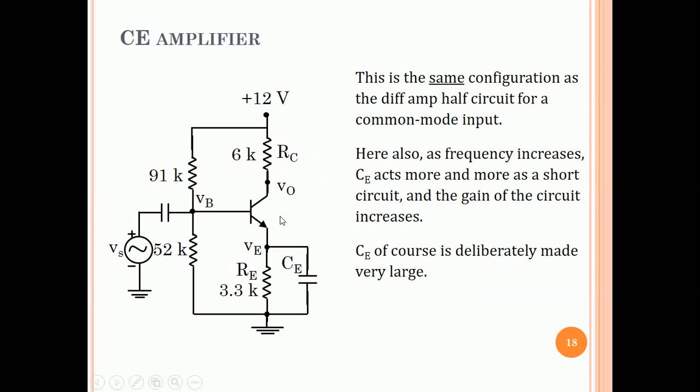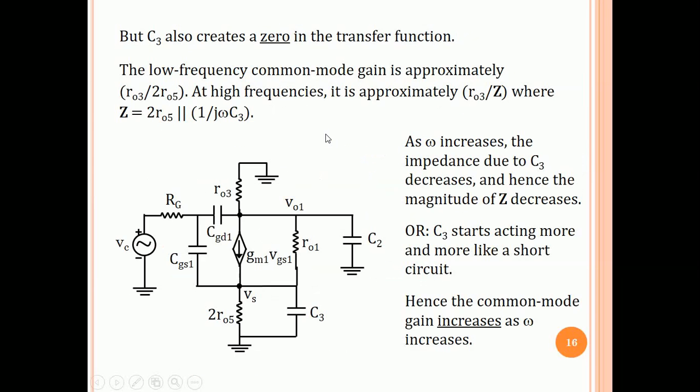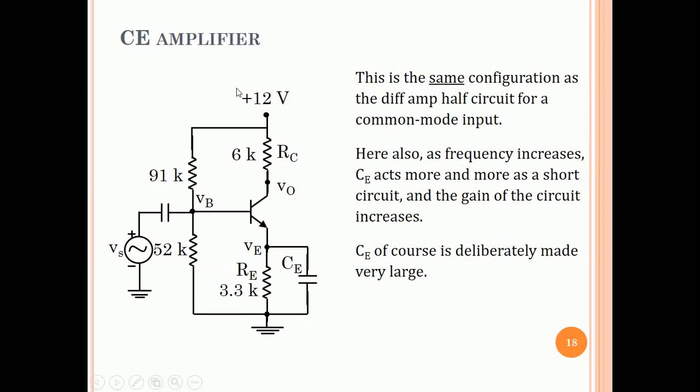I'm sure you remember this circuit, you've studied this a lot in your undergraduate. This circuit, ignoring this coupling capacitor, has the RC, transistor, RE configuration the same as this one. This is the equivalent of RC. This is the equivalent of RE. And this is the transistor, and this is the equivalent of C. It's the same topology as the common emitter amplifier.